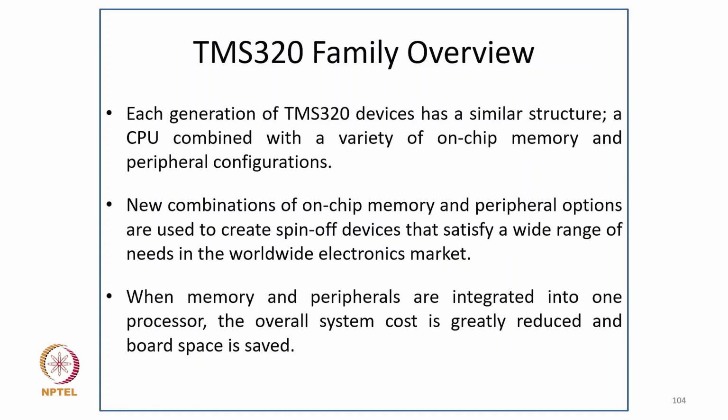Now each generation of TMS320 devices has a similar architecture, a CPU combined with a variety of on-chip memory and peripheral configurations, and new combinations of on-chip memory and peripheral options are used to create spin-off devices that satisfy a wide range of needs in the worldwide electronics market. So when memory and peripherals are integrated into one processor, the overall system cost is greatly reduced and board space is saved.